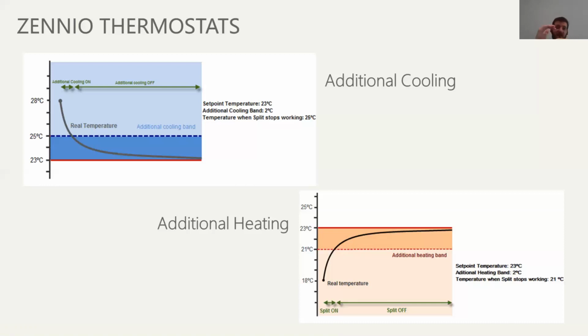So if you have defined 1 degree lower hysteresis and 1 degree upper hysteresis, you will have up to 2 and a bit more than 2 degrees difference in the room all the time. So you probably want to have a low inertia system controlling that, or a smaller 2-point hysteresis band controlling that.